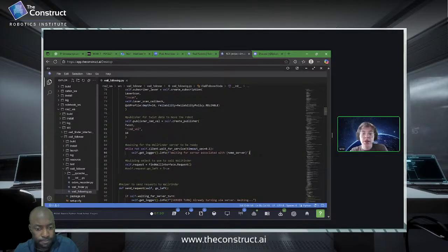And here's an interesting thing I had to do. I have to wait for all of the servers to get ready on the real robot, which actually takes time, whereas in simulation, all of this boots up at the same time, so you don't have to worry about them stepping on each other's toes. With this, I was running into issues for a while where it was trying to just move forward and then the server would activate, and it was causing all sorts of problems.